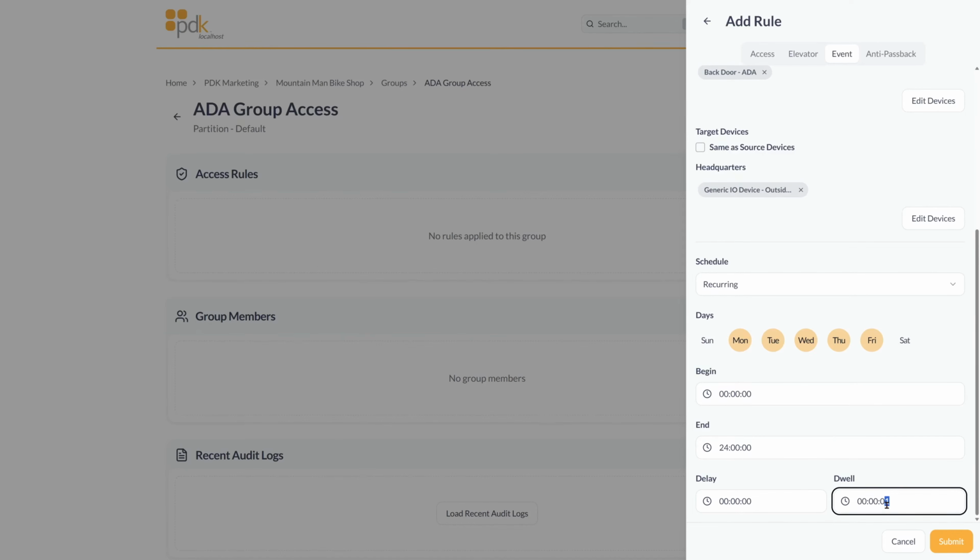I'm going to repeat it again just in case it didn't. What we need to do is program it so that when the door relay is activated, not only does the strike or the mag lock unlock, we also need to complete the circuit. If you go back to my drawings, you'll recall that we had to complete a circuit using the generic I/O device in order to allow that outside button to be activated. If we skip this step in the programming, that circuit on the outside button is never completed, meaning that you can't activate the motor from the outside. That's why this rule is important.